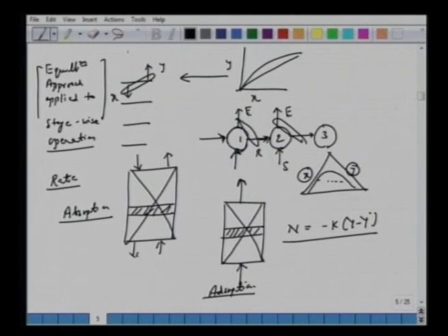After time t, the two streams have been given enough time to mix and transfer the maximum species from one phase to another phase. Similarly here in distillation, at every tray of the distillation there is a pool of the liquid, so that when the vapor comes in and the liquid drops in, there is a mass transfer, there is a rate, but overall our approach is that two leaving streams have spent a good amount of time here, so they are in equilibrium. So we don't get into this rate based approach.